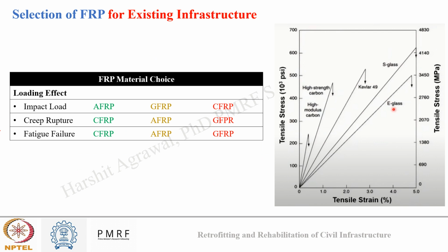Okay. Now on site, there are other types of loading action that can also become critical. There can be impact loading, creep loading, and fatigue loading. Impact loading, we know, is a sudden load at a point. Creep loading is due to continuous exposure to a sustained load, and fatigue loading is loading-unloading cycles that can occur mainly in bridges. We can see these two types of loading.